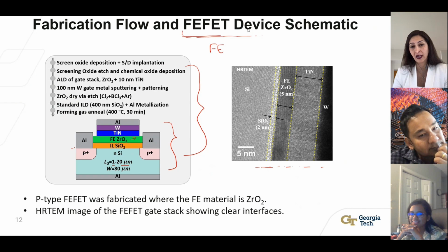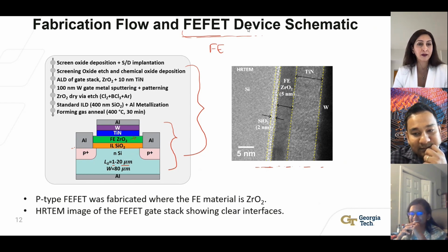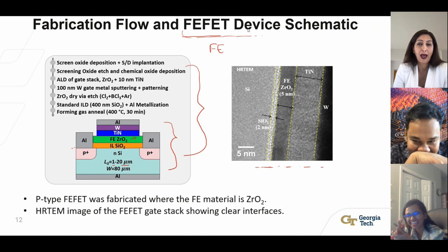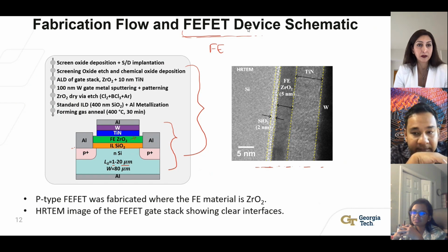I mean, I had Zach going into the clean room yesterday. He couldn't find any aprons for the acid hood, and the Unifilm had some parts that were missing literally on the platform. The Unifilm sputterer, if that goes down, our FEFET process will get stuck. Well, this whole week, I think this tool is down. Every time we use the Unifilm, we are throwing a couple of wafers away, I think, every 2 runs. 2 wafers out, we can process only 1 wafer, even for the bottom electrode at this point.